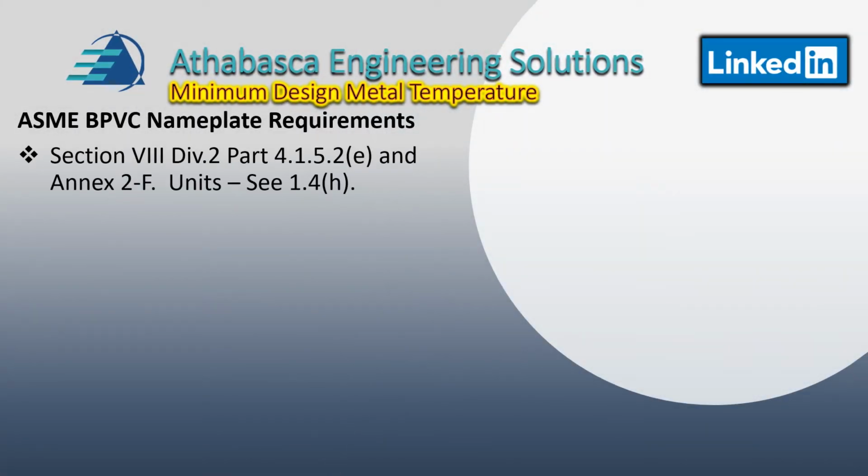About the nameplate requirements, what you'll find in Division 1 is that most of the requirements are in UG-21, whereas in Division 2 most of the requirements are in Part 4.1.5.2E in the 2021 version. There are also very specific requirements for stamping and nameplating, right down to the letter size, everything in Annex 2F. A discussion about the acceptable units is found in 1.4H, and typically the client has specific requirements.